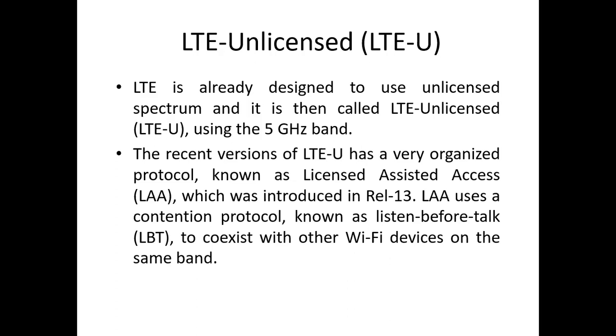But you have to be very careful. The key problem for unlicensed band is that it is free for everybody. It's not only free for you. You're not paying money for it, but you need to understand that other people can also use it. So there is a possibility of interference. There are chances that you won't be successful in your operation. So you have to check which part of the unlicensed band is free currently, and then you can use that.